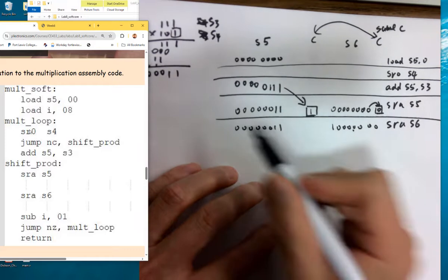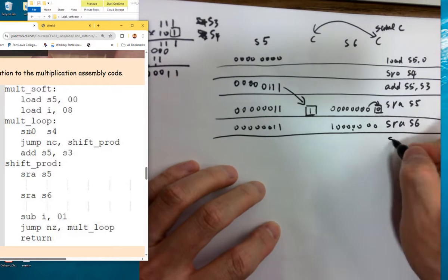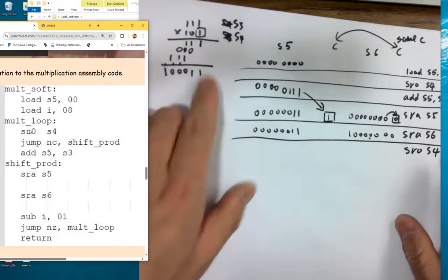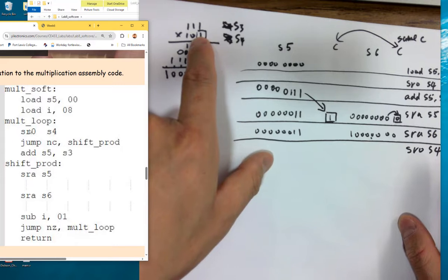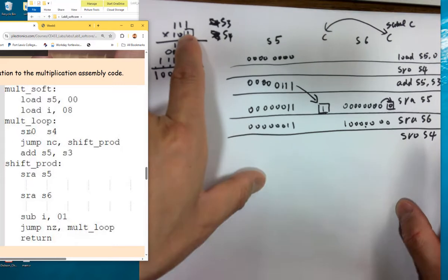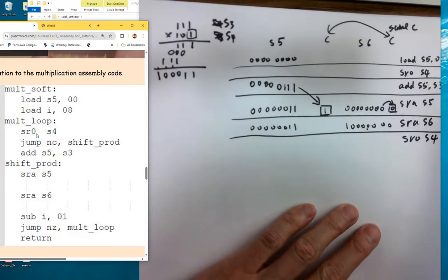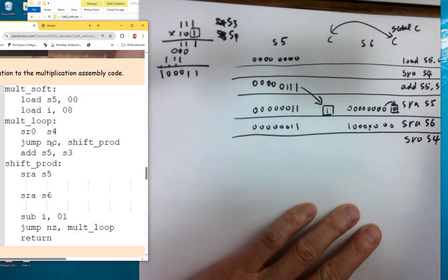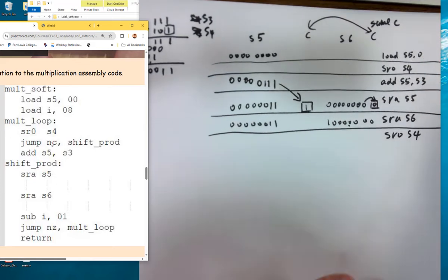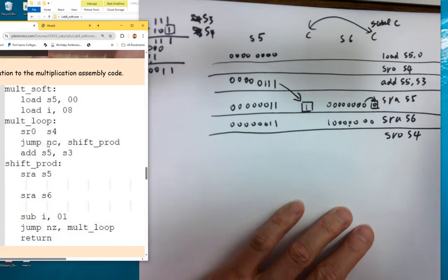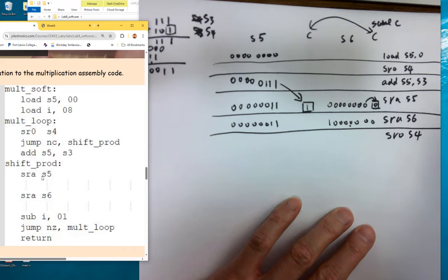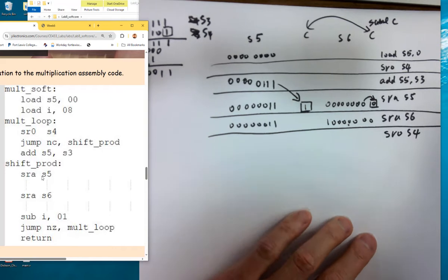What's the next instruction? What is the value here for the next bit? 0. What's the next if it's 0? So it's non-C, right? So carry is 0. Carry 0 so it's not 1. So not 1 means not C, okay? Don't do the addition, which makes sense, right? It's a 0, you're not adding anything to it. So directly it goes to shifting. Just not adding anything, but shifting.